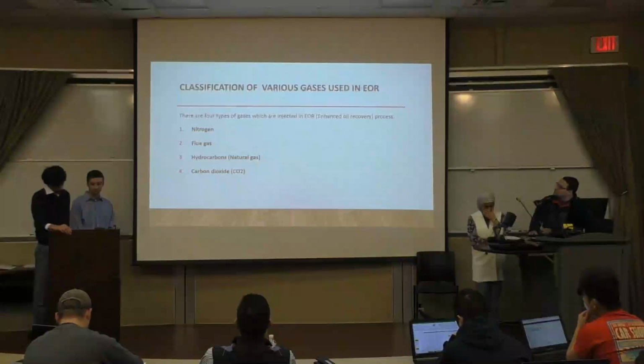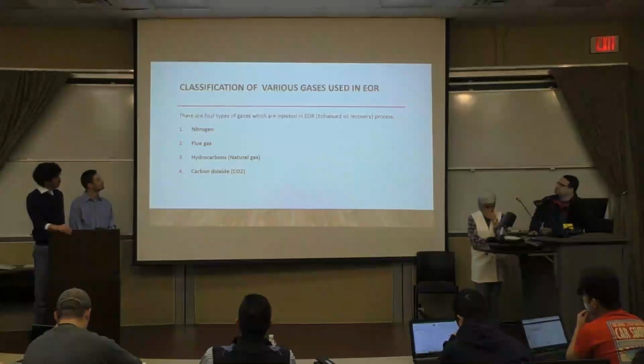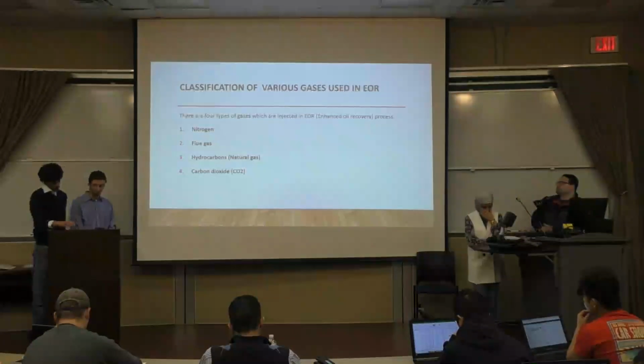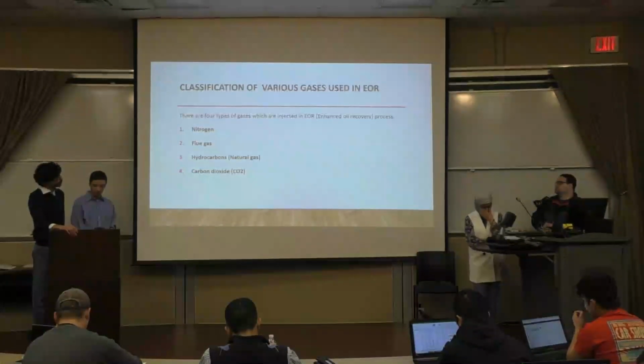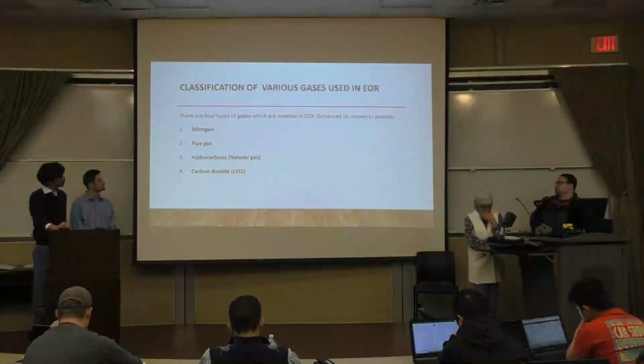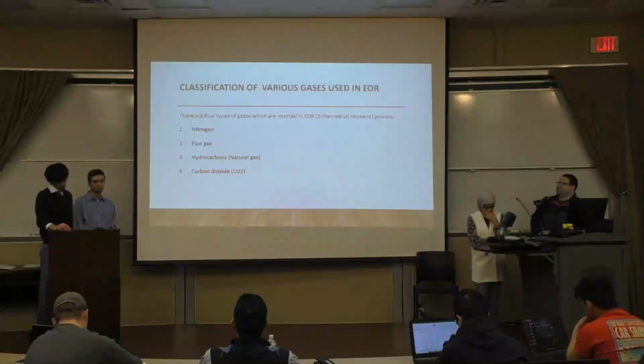Nitrogen and flue gas have a common strategy. These gases are cheapest, low recovery cost, and minimum miscible pressure, which causes the gas to be miscible in oil. Their viability is limited to deep reservoir due to the high miscible pressure.